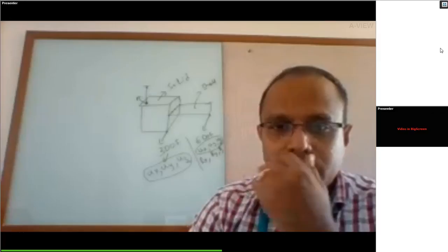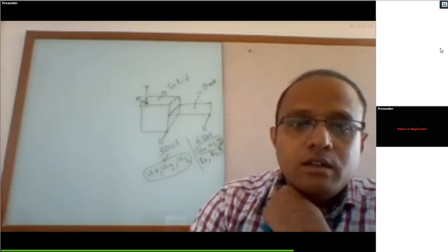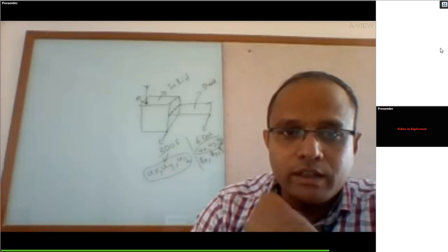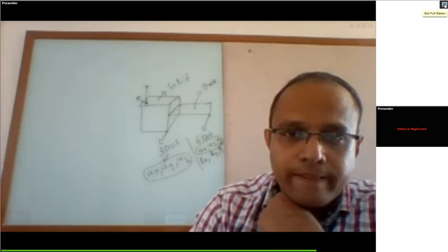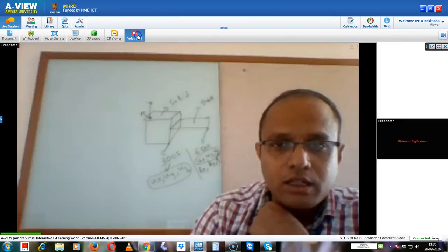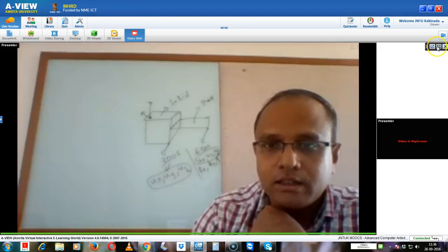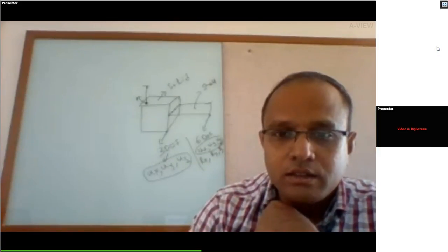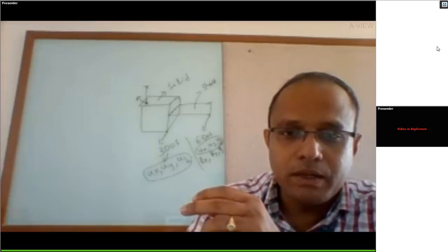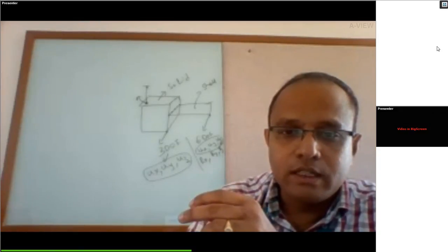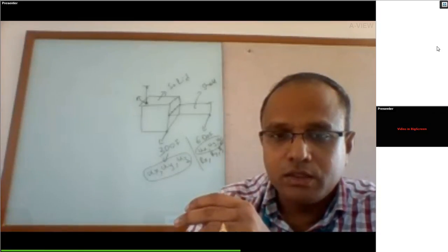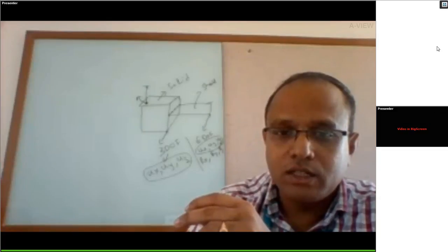Here we discussed how at the interface areas we match the mesh pattern and then use couplings. This is also related to how the mesh is matched at the interface location. When you give couplings, see the displacement pattern: at the interface location there is no change, and a smooth gradient exists, similar to other locations.